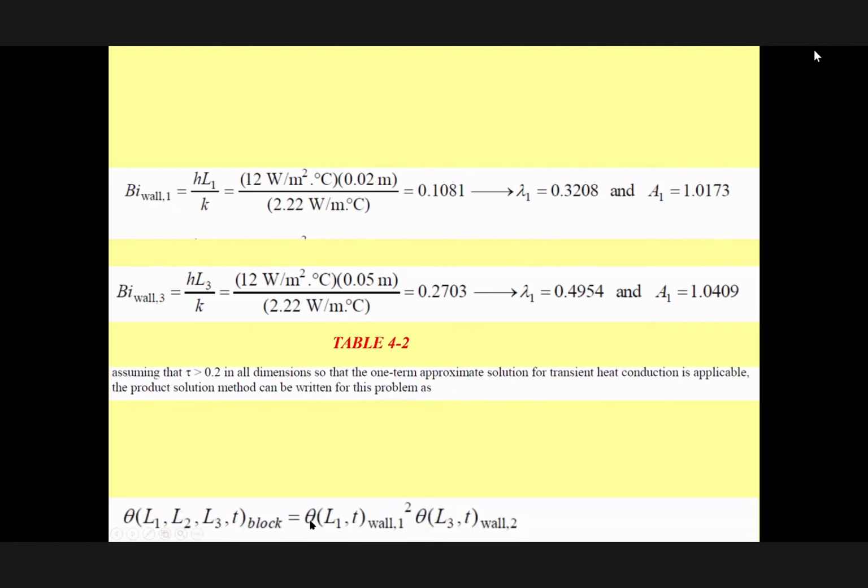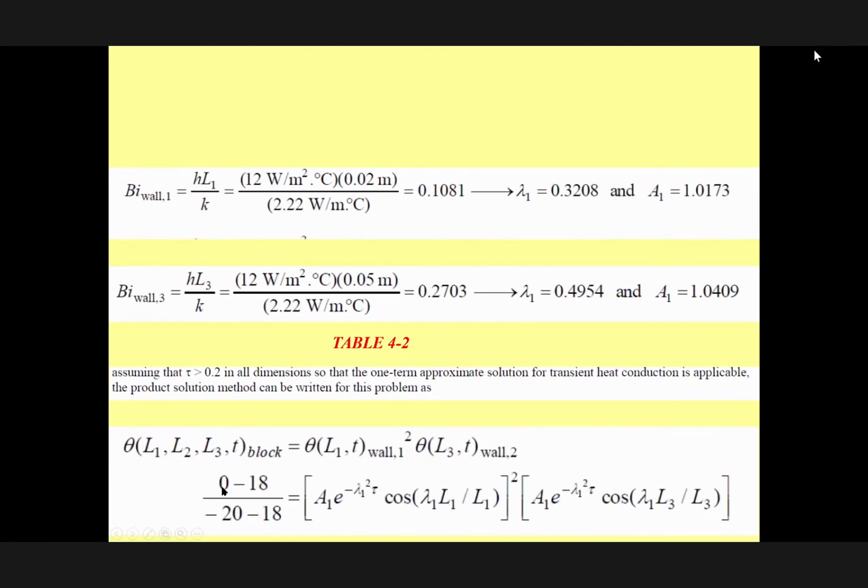Therefore, here we go step by step again, and here is the equation. Here is the temperature at which melting occurred, the ambient temperature, and the initial temperature here. This is looking at one surface, and this is related to this surface, because I'm trying to find out when the temperature at this point becomes 0. This equation is for one plate, and this equation is for the other plate. We calculated A1 and A2 from both parts here. We have this one and we have this one.